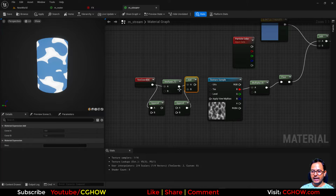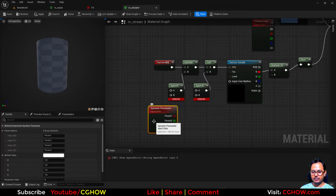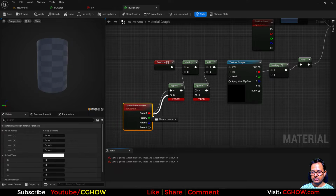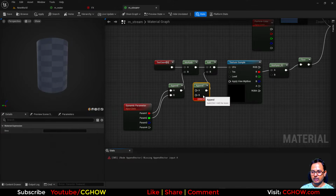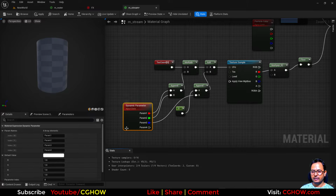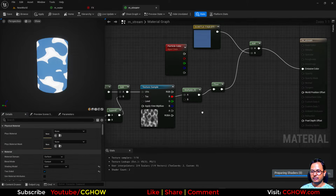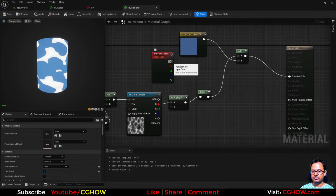So this add is for offset and this multiply is for tiling, and we have two appends, and I'll take the dynamic parameter, and here we just need y, so in x I'll put that, and this will be my x tiling, y tiling, and this will be my pan, and that's it.